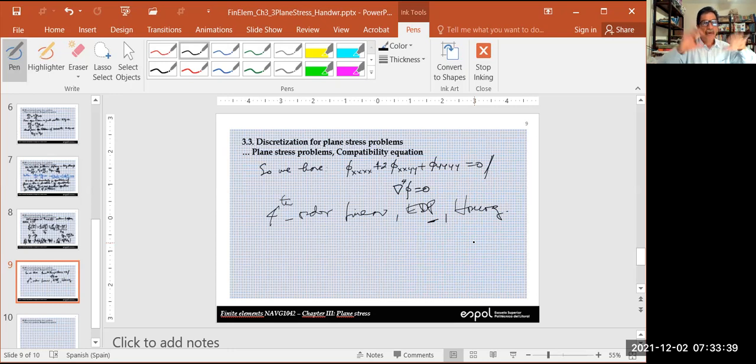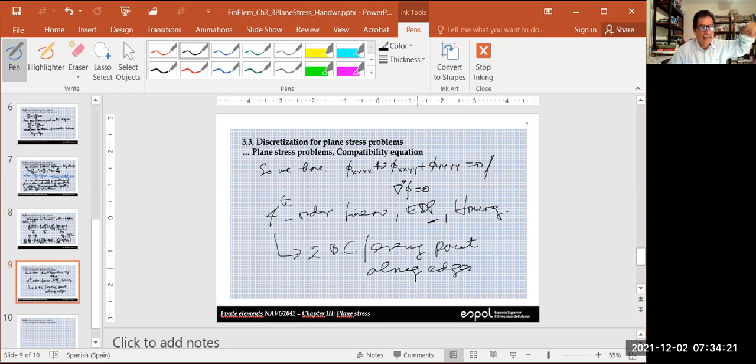If you have a plate like this and you apply no force, I mean, there will be nothing. It's just the plate, that's it. So if you have the plate but apply a force, in the point when you apply the force, you have to set a boundary condition. But that's going to be different than zero. Okay, so as you say correct, this is a fourth order linear. So if it is a fourth order, you need two boundary conditions for every point along the edges. So in every point of the boundaries, which are the edges of the plate, you need to specify two conditions.